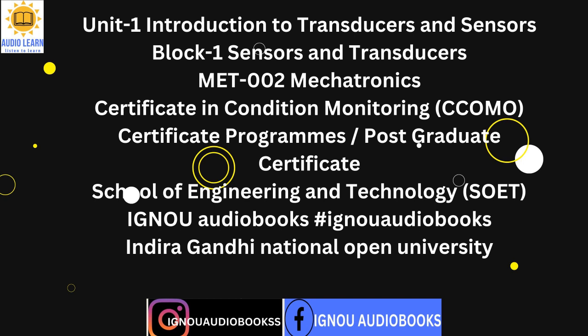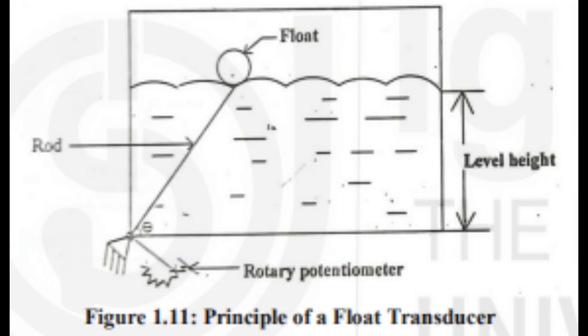Unlike the rotary potentiometer, it will not lose accuracy due to wear. The high precision of the resolver is usually limited by the AD converter, which converts the analog voltage into a digital count. Typical AD converter incorporated RDCs have 12 to 16-bit resolution.